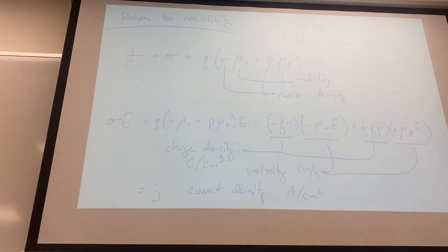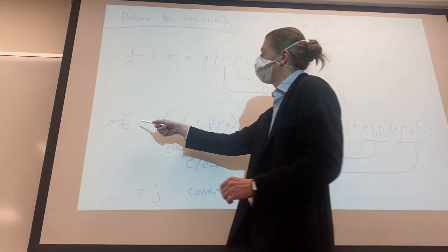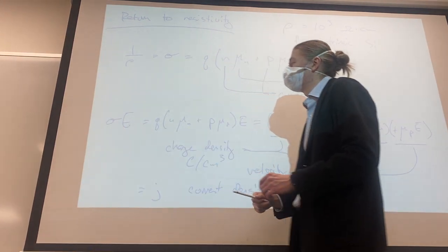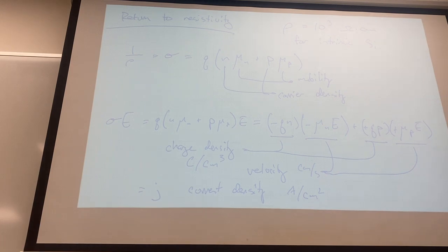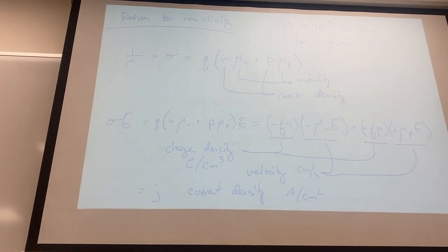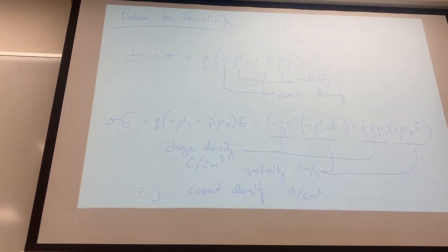We've got something that kind of looks like Ohm's law, right? We've got a current density, we've got an electric field, and we've got conductivity. It's close, but not quite. Multiplied by all the actual dimensions in order to get real voltages and currents and resistances. It's sort of a per unit size, per unit area, per unit volume equivalent.